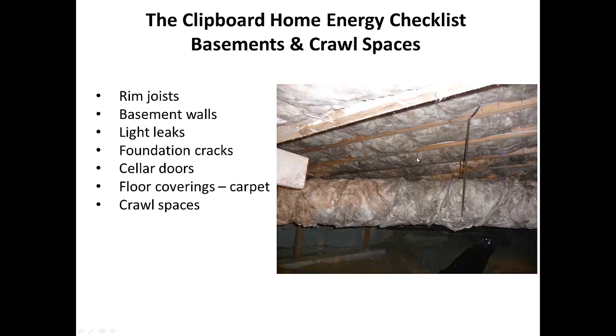And if you've got a pipe running through here, what you've done by insulating is you've taken that pipe that was relying on the heat coming from up above to keep it from freezing, and now that water pipe that runs down through here is not going to be warm anymore. And so it's going to freeze, and you're going to have a broken pipe.